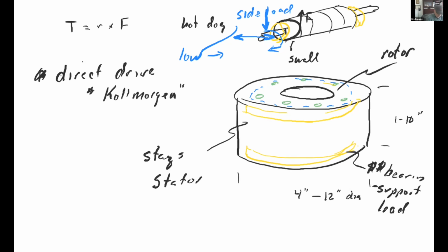And then there's also usually one for axial load, but most of the time that's much less of an issue. It's the side load, because you get torque out of the motor, and torque pushes something one way here and the other way on the bottom. Sometimes they don't even list it. And if you take these motors apart, a lot of times these NEMA 17 motors don't even have bearings. They're just bushings inside. They're only designed to rotate.